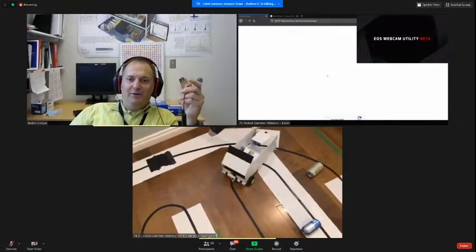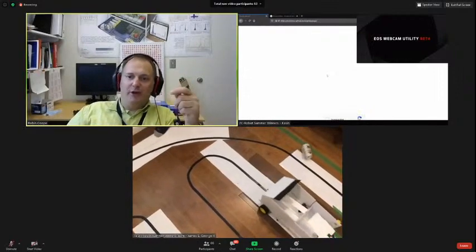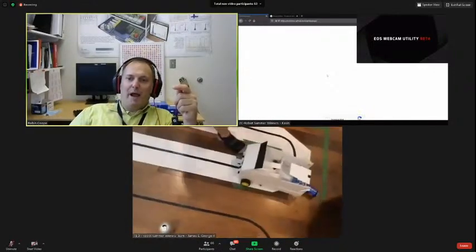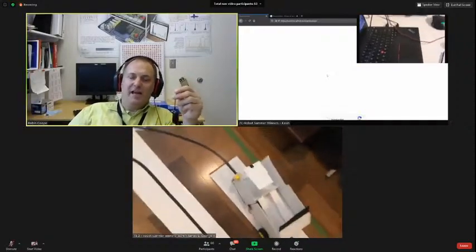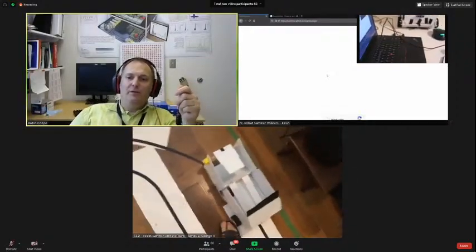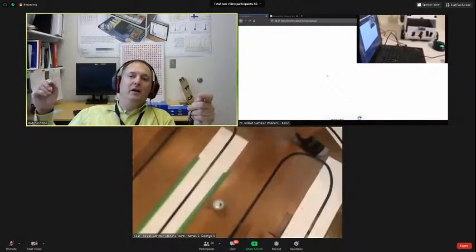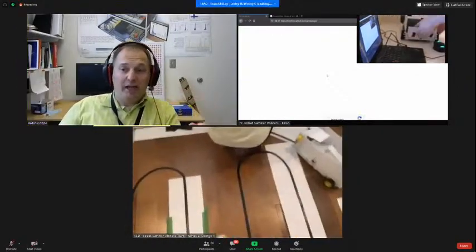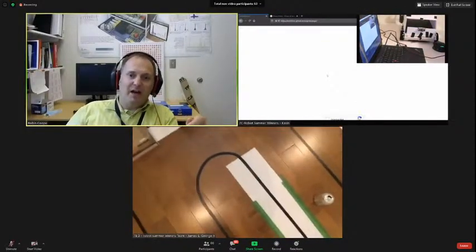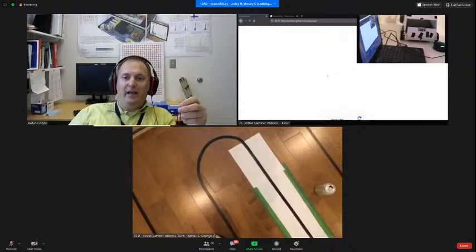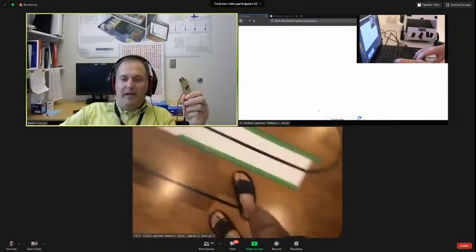It works well now. If people are wondering what this means, the PD values are the control parameters of how it looks at not only the error between where the tape is and where it wants to be, but the velocity, the amount the error is changing. This is a major subject you learn in mechanical and electrical engineering in undergrad, feedback control. And clearly, it sometimes works, and it sometimes doesn't work. There's an issue. Anyway, it looks fine.